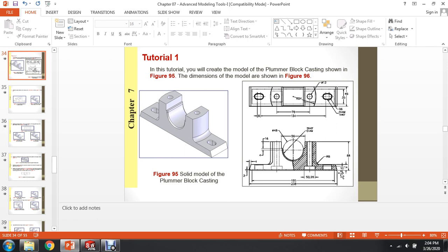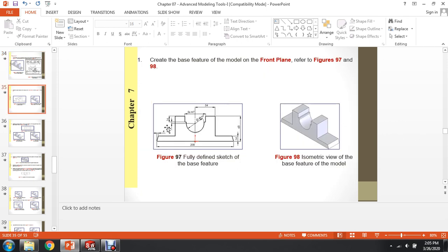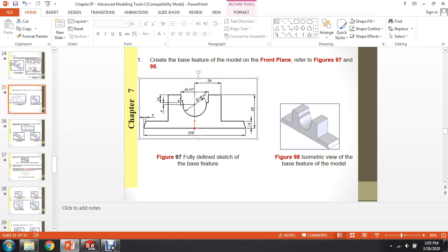I don't know the extrusion length exactly without doing some calculations. So you can start with the front view, and actually this is a sectional view they have given, half section, and without the holes and other material removal sections, we will draw the front view. What to draw first is the next question. So better you start with this easy front view. In the next slide they have given the front view to draw. This is not given in the exam, so please make sure you understand what to draw first.